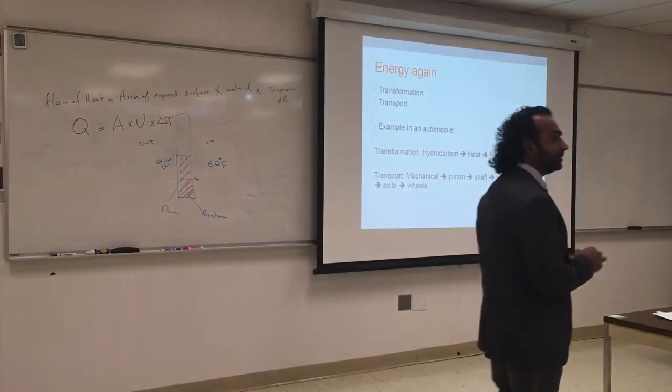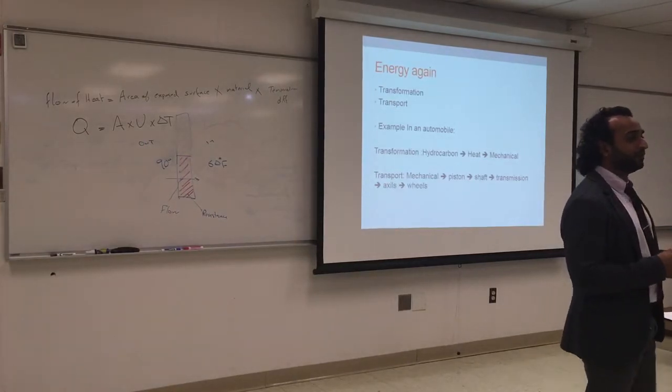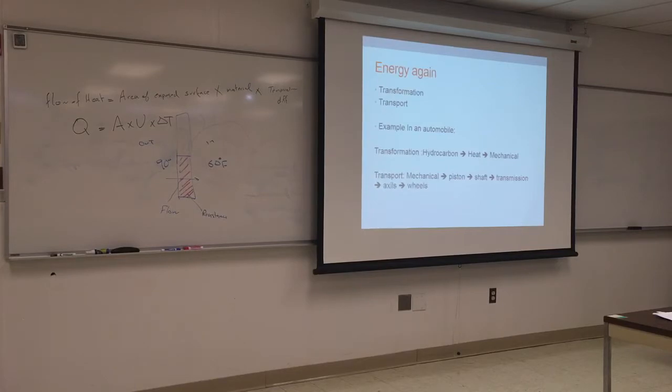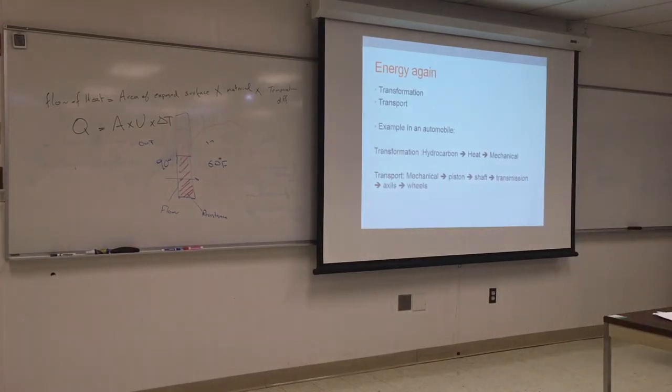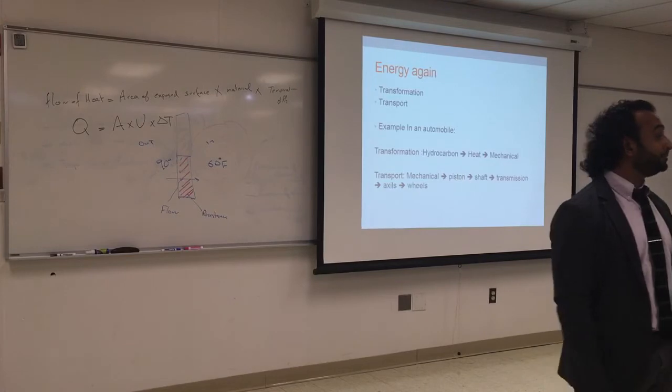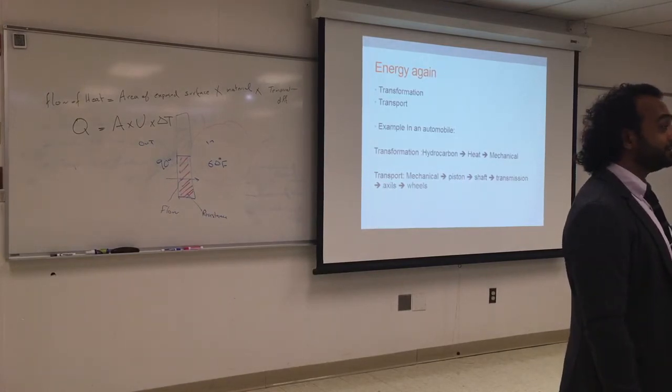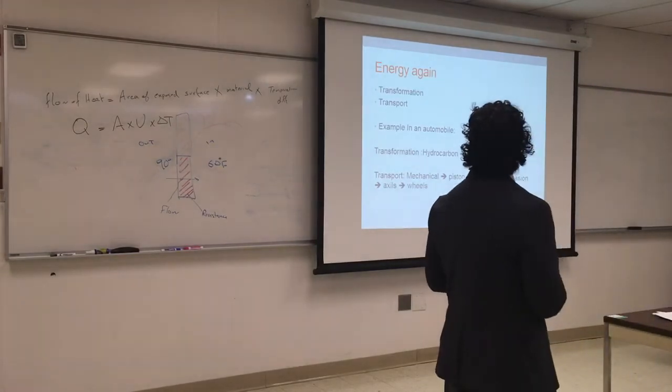Easy. Are they as reliable as the gasoline engine? I didn't look at the reliability, but electrical motors usually are way more reliable than an internal combustion engine, because they have fewer moving parts, and some motors don't even have friction in them. They have levitating bearings. So the less friction, less interaction, the more reliable they are. And electrical motors, if they're well built, last for a long time because nothing can deteriorate them. The only thing that usually goes bad in a motor is the bearing. It's always a bearing problem or an overload problem. You shut the motor with a lot of voltage and it burns. Other than that, they can last for a long, long time. Probably you have some equipment from the 70s still running. If it's just motors, it will stay for all time.